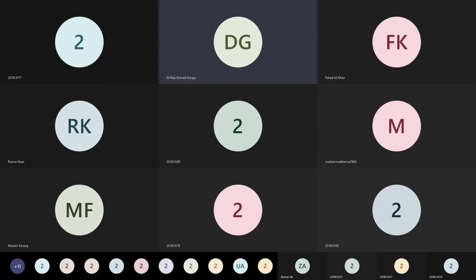There are some other points which are helping tools. Analysis of a truss can also be started directly from that joint where at least one known force exists along with a maximum of two unknown forces.